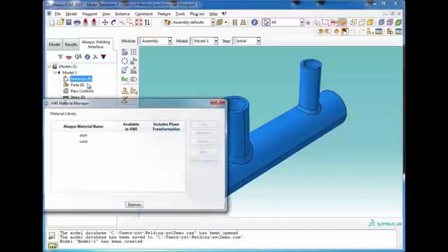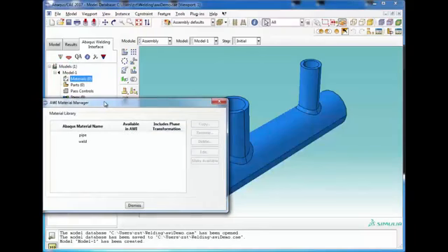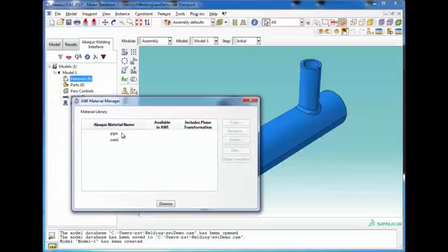This one, the manager. Okay, so the material manager displays which materials are available for the plugin to be able to use. And at this point, it shows no materials are actually available to be used by the AWI. It shows that there are materials that have been created, but we can't use them yet in the AWI. Now, the reason being is that the material properties that you would have created in Abaqus CAE, like the elastic, the plastic properties, thermal conductivity, and all of that, define just about everything we need. But we have to add one more thing essentially.